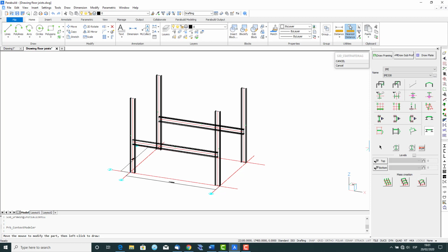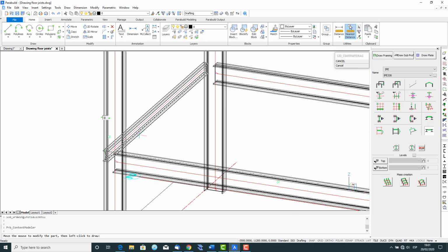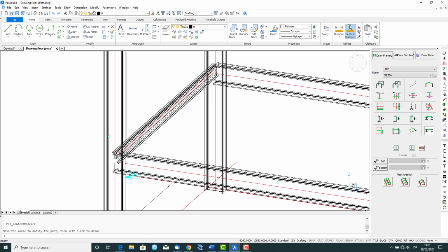Place the cursor between two beams and a new beam will be placed with the reference dimension referring back to a fixed point. This may be a column line or another beam. Then move the mouse cursor until you see the required dimension, and when you're satisfied, press the left mouse button to accept.